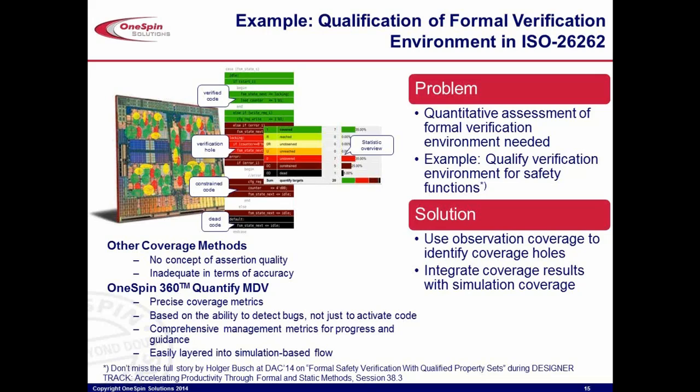We also do this, so we have a concept of observation coverage, which goes a little beyond the normal structural coverage, and the goal of this is really not only that the assertion executes these lines, but that the assertion is really checking this line, and if there's a bug in this line, it must be caught. And on one side, this really helps novice users also to guide their work to see if they are covering what they expect with the assertion they write.